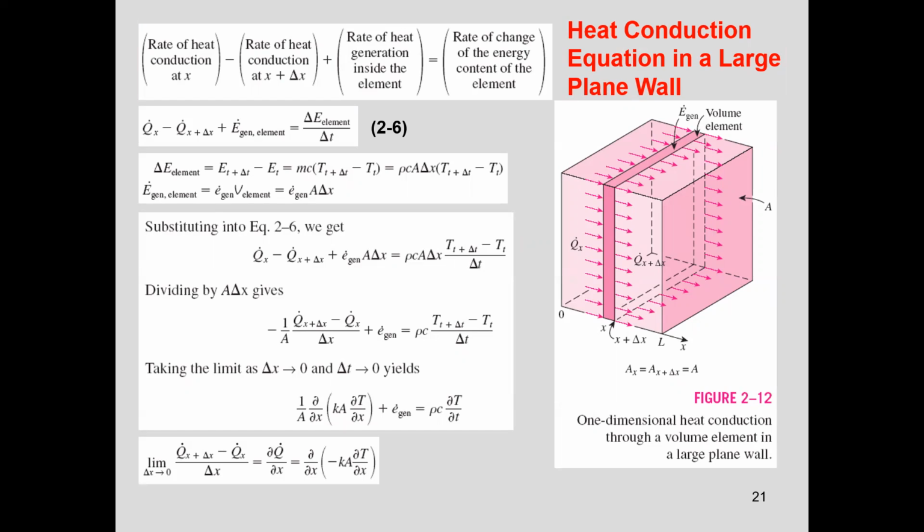So the heat conduction equation in a large plane wall: to start with, we have to understand that the rate of heat conduction in one direction, that is the x direction, minus the rate of heat conduction at a short distance delta x, plus the rate of heat generation inside the element is equal to the rate of change of the energy content of that element.